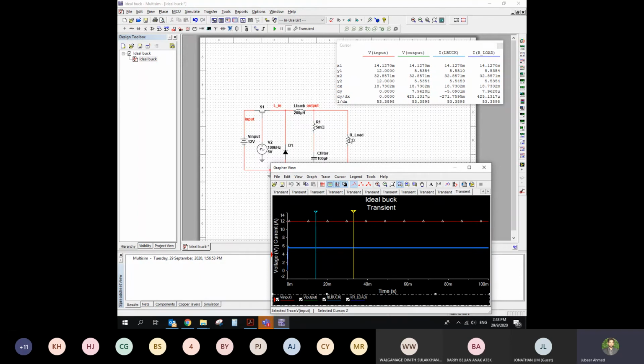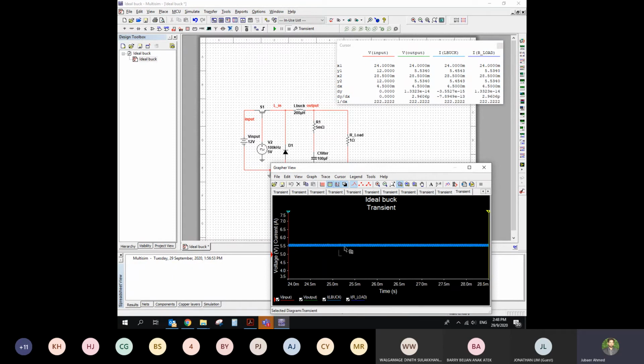When the output current is affected, you can also see that our inductor current is affected as well. Previously the inductor current ripple was 1.1 to 1.2. Now the inductor current is about 5.4 to 5.65. But if you find the difference here, the peak to peak ripple remains the same. So the threshold value will keep changing, but the peak to peak ripple will be exactly the same.